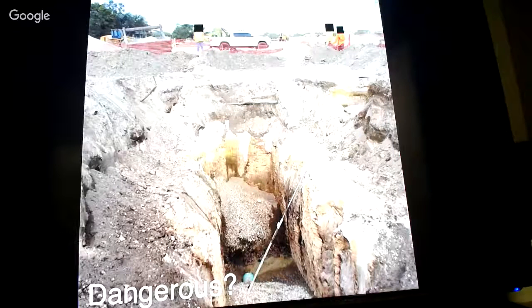Not only that, if your emergency response is to call the fire department or emergency medical services, what are they going to do that you can't? Are they going to bring their own excavator out there and start trying to dig the guy up? Are they going to jump in the hole? Probably not. So that's why it's up to you guys to respond quick enough so that you can save somebody if they need saving. So, no trench box, sheer sides, no egress, very bad situation.